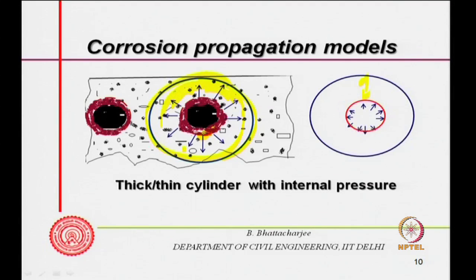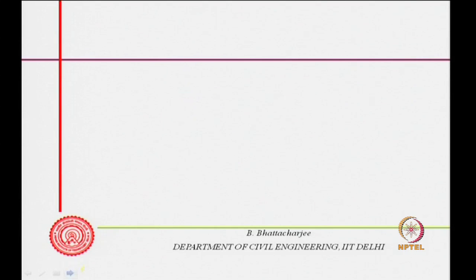Also, the properties of the rust product, their modulus of elasticity, and several other situations, such as what kind of problem you take it as, a plane strain problem, and whether you take uniform pressure in the surrounding system or uniform strain in the deformation. There are complexities involved in this modeling, but this is how one can visualize what happens, and this can result in the cracking of cover concrete, which is defined as a service line. So, these are further, more sophisticated theoretical models.